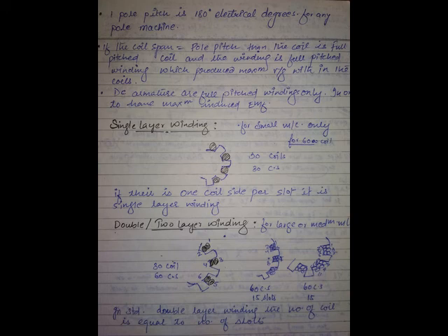All the 8 conductors are arranged in how many paths? 4 parallel paths. By cutting flux, each conductor can produce how many volts? 1 volt each. So what is the total output? 2 volts. Each path can bear how many amperes? 1 ampere, right? That's the common thing.